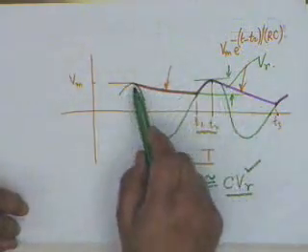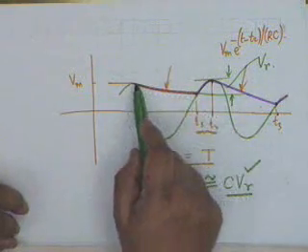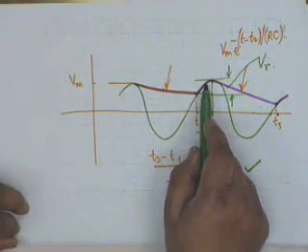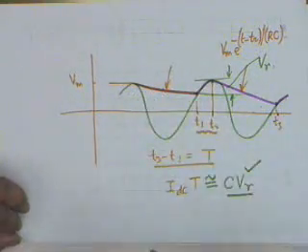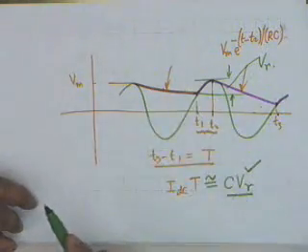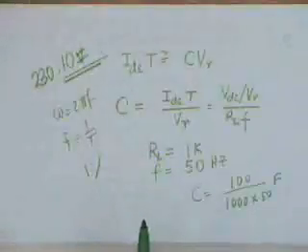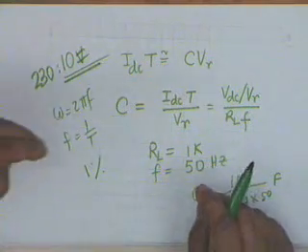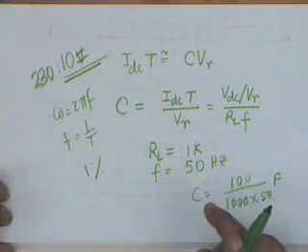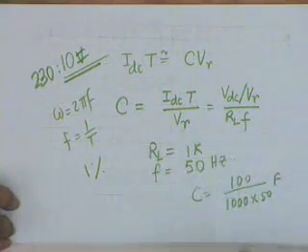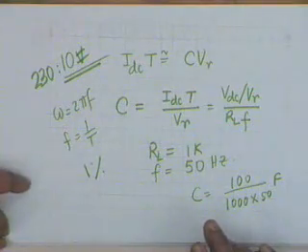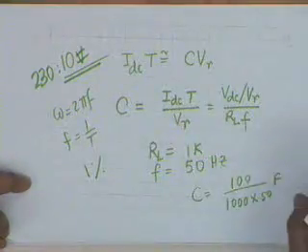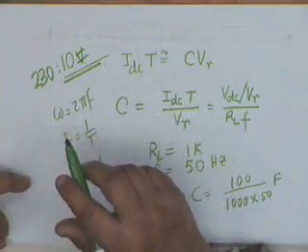Okay. You see, VDC, ideally, if the capacitor was infinitely large, if RC product was very large, then the ripple voltage would have been very small, and therefore the capacitor would have discharged very slowly, and therefore the DC voltage would have been approximately equal to VM, the peak value. In this example, we have specified that the ripple voltage is only 1%, and therefore the voltage across the load can deviate from VM by only 0.01. Can it increase by 0.01? No, it's decreased because the capacitor decays, and therefore VDC is approximately equal to VM.